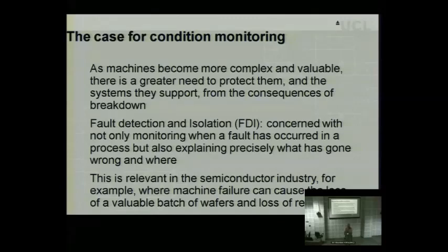You want to be able to map your injection signals onto the faults in each channel, which you can do if that matrix is invertible, the one at the end. If it's not invertible, you have to be a little bit more careful. But there is nothing in what we just spoke about that says you can't have multiple sensor or actuator faults, or indeed have them in many channels. So long as the channels are there, then you can estimate more than one fault.